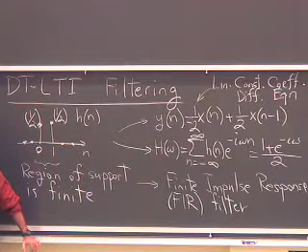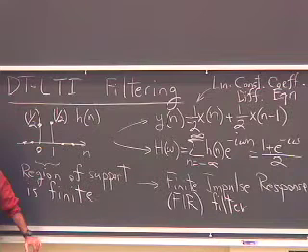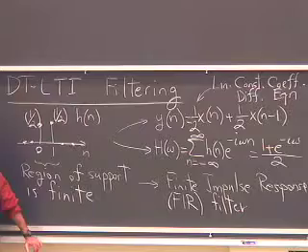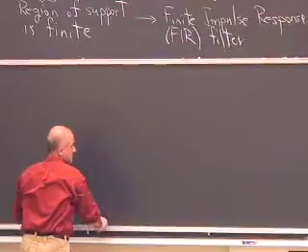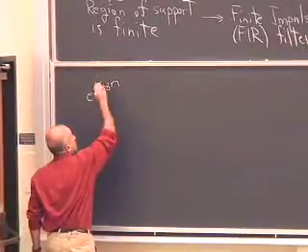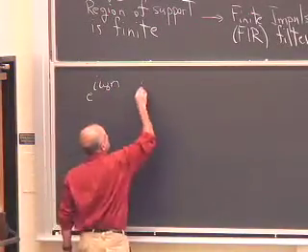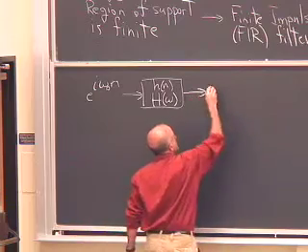Last time we saw that the magnitude response pretty much is the filter. But what's the phase response? The effect of the phase is more subtle. I'll go over one example in class where you apply a sine or a cosine to a filter like this, and you'll see what happens to that sine or cosine at the output. You can see the effect of the phase most conspicuously by applying a complex exponential of a particular frequency to an LTI system whose impulse response is small h, frequency response is capital H.